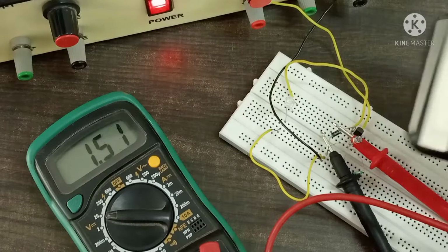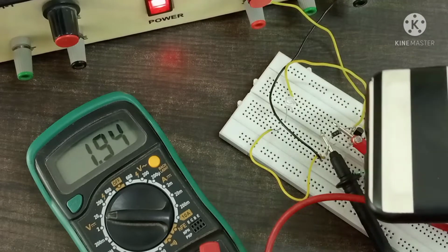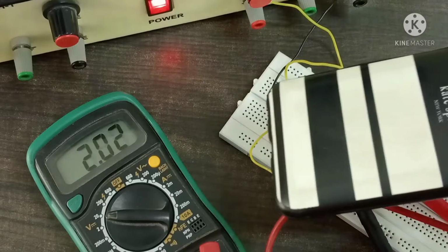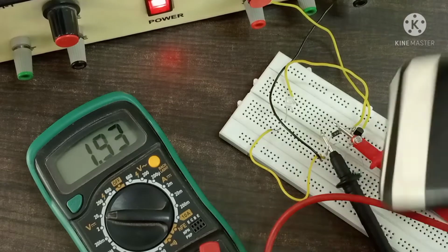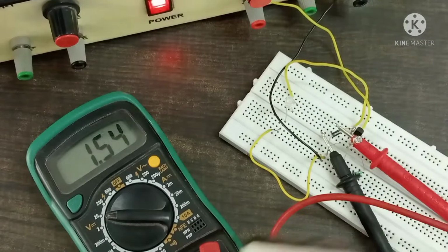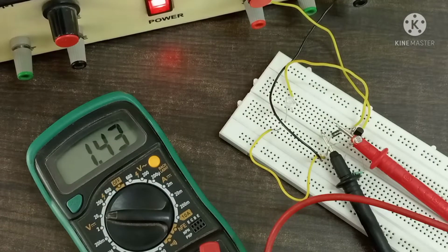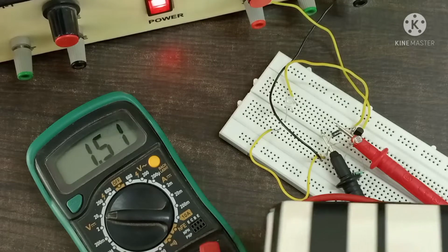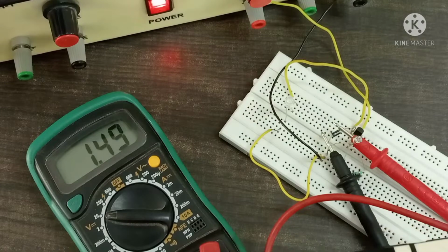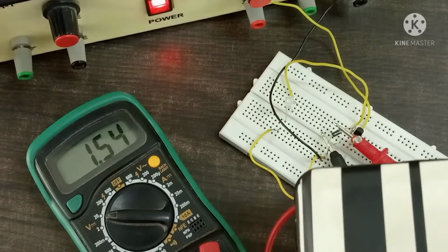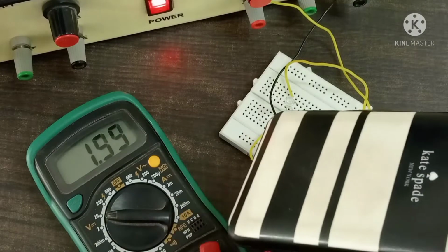Okay, so this increase or decrease of voltage due to variation in the resistance of this LDR causes this sensor to work. If you have the concept of LDR or transistor and the different circuit components, then you can apply this. Now you can see right now the voltage across this is around 1.5. For this white LED we need a voltage around 3 volt, it may be a little bit less or more than that, but around that. Since it is much less, that's why this LED is not glowing.